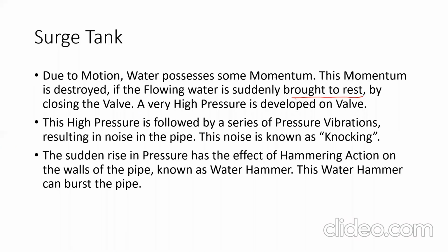This obstruction is due to closing of the valve. A very high pressure is developed on the valve and in the penstock. This high pressure is followed by a series of pressure vibrations, resulting in a noise in the pipe, and this noise is known as knocking. In the exam they may ask what is knocking. Knocking is because of this.